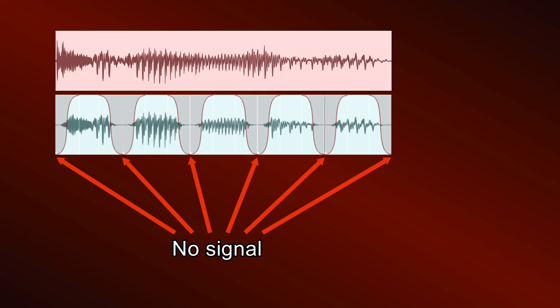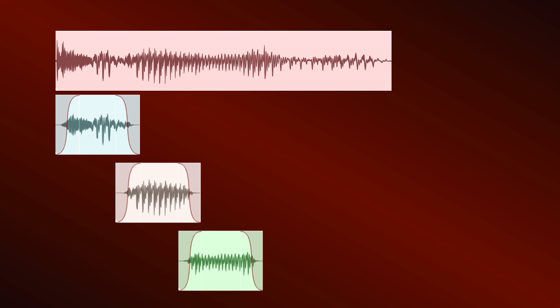You see, if the analyzer recklessly cuts off audio into chunks, each chunk will have a click at the beginning and the end. As you probably know, a click has a very broad spectrum, and this spectrum will be added to the spectrum of the chunk. As a result, the analyzer will print a different result in comparison to the actual one. To avoid that, a decision was taken to apply a fade in and fade out to each chunk of audio. That's good, but now we've got zones where the signal is missing. To fix that, the chunks should overlap each other.